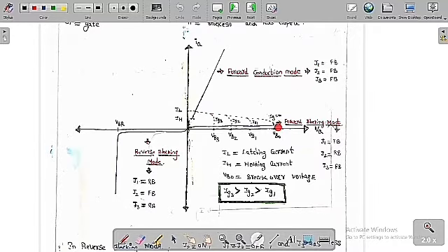Suppose a gate current is applied. Then the reverse breakdown voltage of junction J2 is going to decay, and it decays more if you increase the value of the gate current. So now we can turn it on in a very small amount of time. If you increase the gate current, the breakdown voltage of junction J2 decreases.